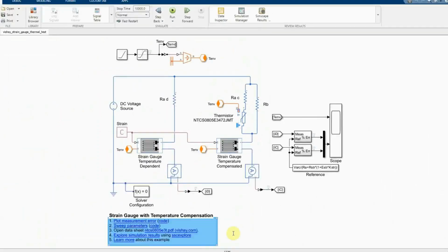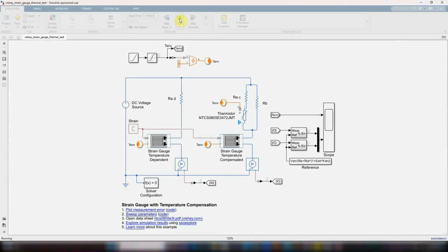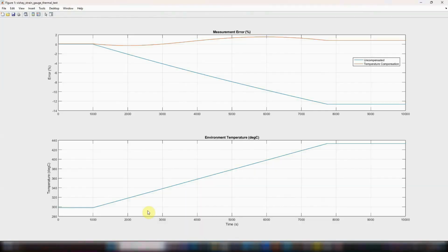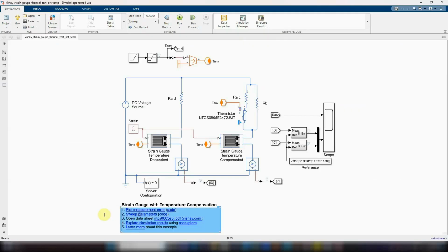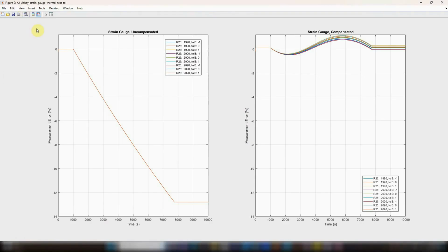of the temperature. While we are sweeping the temperature toward the total temperature range for a fixed strain, we see clearly the reduction of resistance variation in temperature from -13% to less than 2%. Evaluation of the effect of the NTC tolerance is of course possible, and we see here that the introduction of these tolerances does not degrade too much the results of temperature compensation.